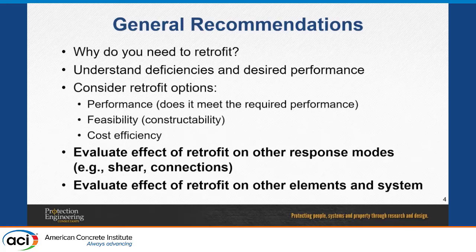Now, the last two are more technical, more structural, and I think those are the most important. It's that you have to evaluate the effect of the retrofits on other response modes. What do I mean by that? As one example, most of these retrofits are for increasing the flexural capacity. But when you increase the flexural capacity of a member, you are increasing the shear demands. And if you don't consider that in the design, you may be introducing a failure mode that you were not accounting for. So if there is one takeaway from this presentation, it would be that one, I think.